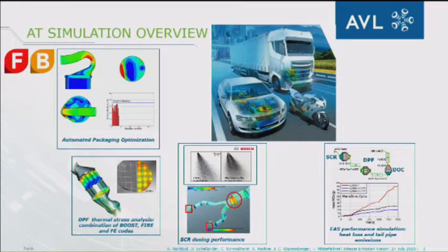Another one is DPF thermal stress analysis. We know that during the soot regeneration process, the temperature can significantly increase, especially if this is an uncontrolled regeneration.